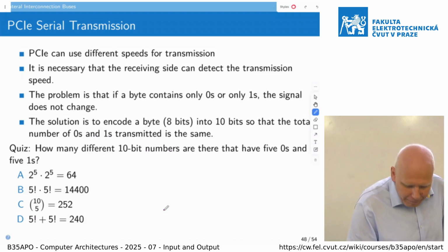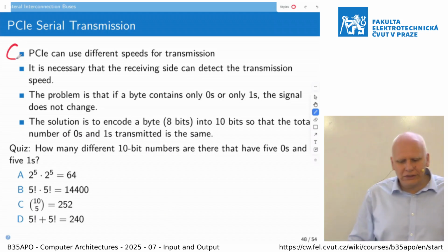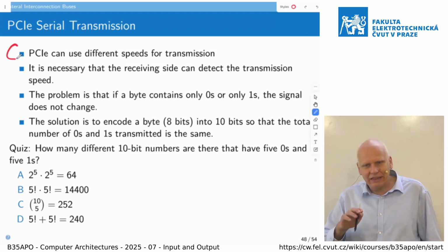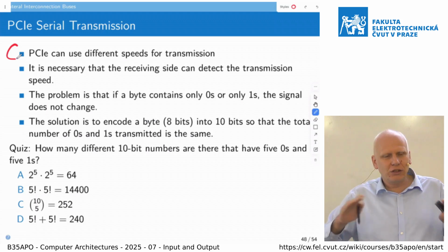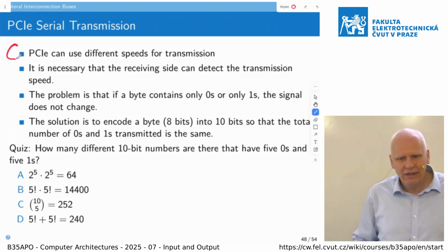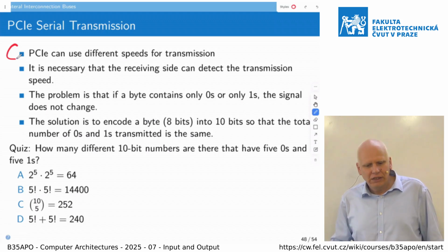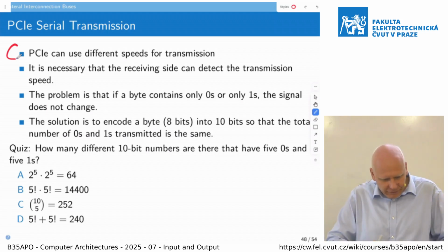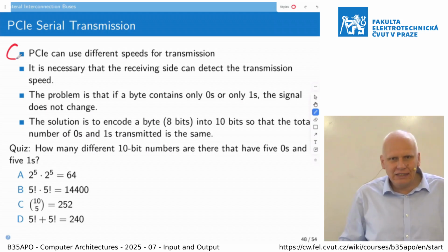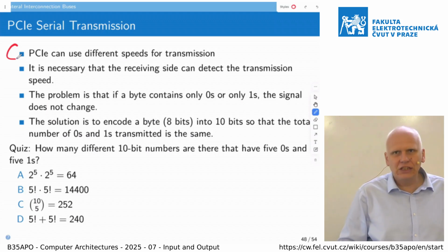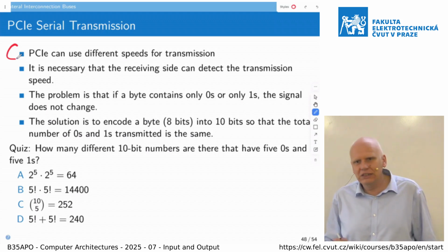But due to the requirement to send data as differential and allow that separation of the ground through the serial capacitors, we suppress the common mode interference and noise and so on. That's great. But we need a signal which has a 0 DC component.